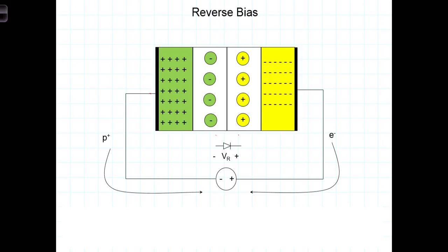So under a reverse bias, we have effectively opened up the switch and made it so that current cannot flow through the diode. So just to review then, diodes will conduct when a positive voltage is placed across them. They don't conduct when the negative voltage is placed across it, and it serves effectively as a switch and can disconnect the terminals here. No current will flow through it.